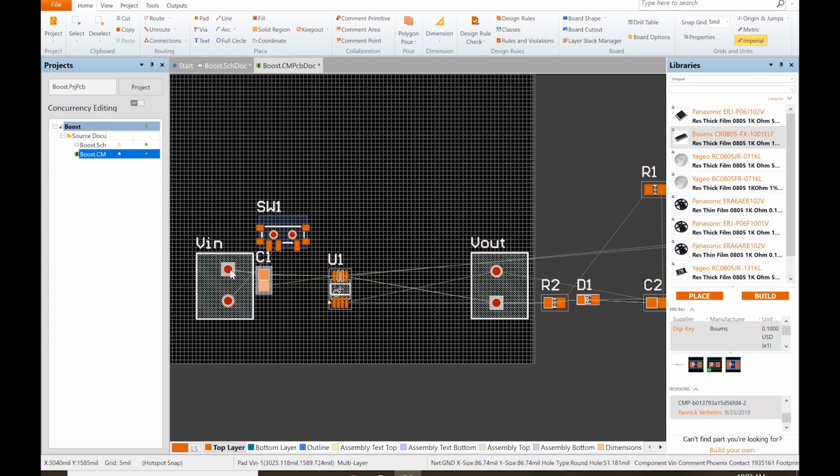And so one of the things that I really wonder about is, so this is going off to the side here. And really this switch should go at the bottom over here. Now I want to rotate that, press spacebar twice. And I'm just going to put that here, put the capacitor there. So now I don't have these wires crossing. And then the input flows to this pin and then will flow off to this pin.